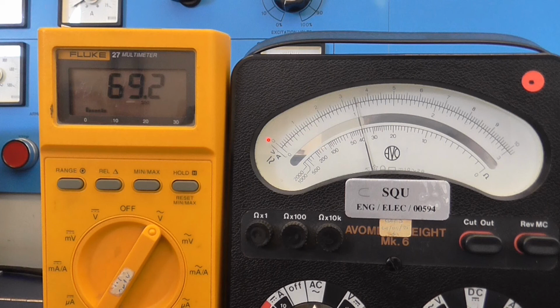Now we'll continue. Write it down, 69.2, and the current is 35. You can write it 69.3, it's almost the same. Take a note that 63 is the knee point. So now we know the knee point. Let's now increase the voltage more and see how the current is increasing rapidly. Try to take more points for your table. I'll just leave this one for you. I'm going to increase it now. See how the current is increasing fast.